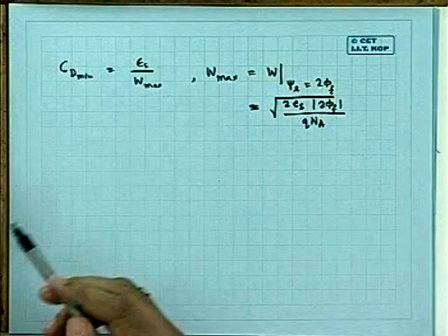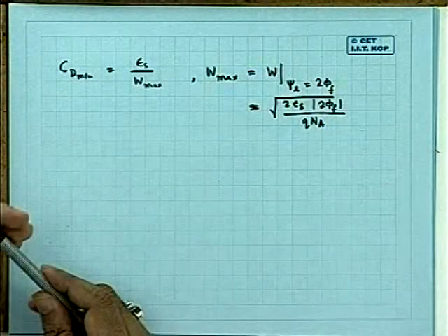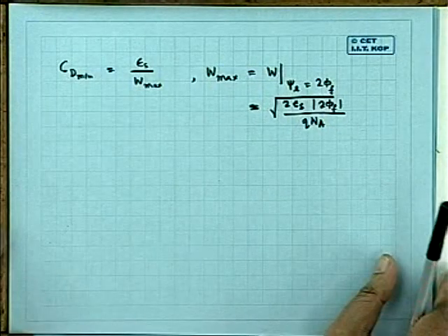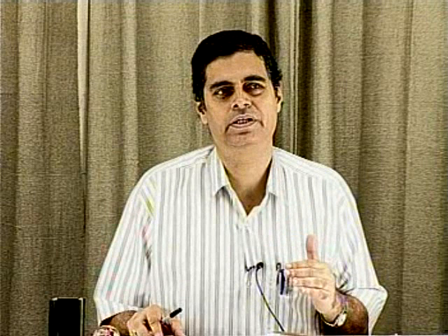So if I make it such that the concentration of electrons is equal to the substrate concentration, there are many ways of defining the threshold voltage. A dynamic definition is different. This is a static definition. We say that it is a point just at threshold, but then for strong inversion we add some quantity, maybe 2 Vt or 3 Vt or sometimes 6 Vt.